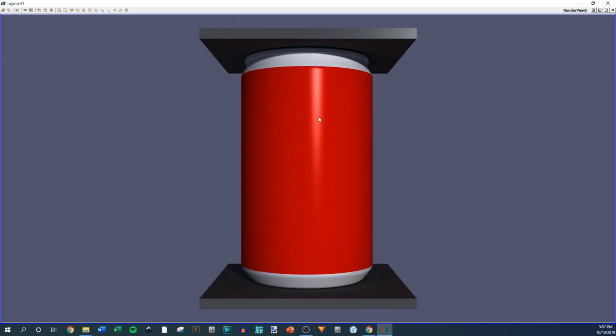If you don't want a super fine mesh just for videos, you can get a reasonable mesh for calculations, and then bring it in here and refine the mesh with the triangulate and the subdivide to get good looking videos. And you can render it out and have this really nice, realistic looking image.